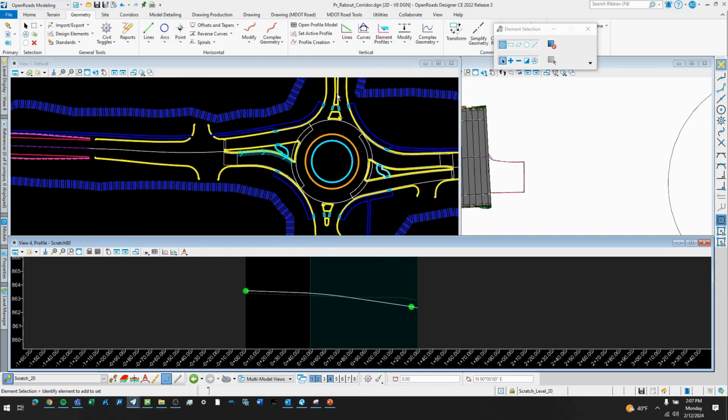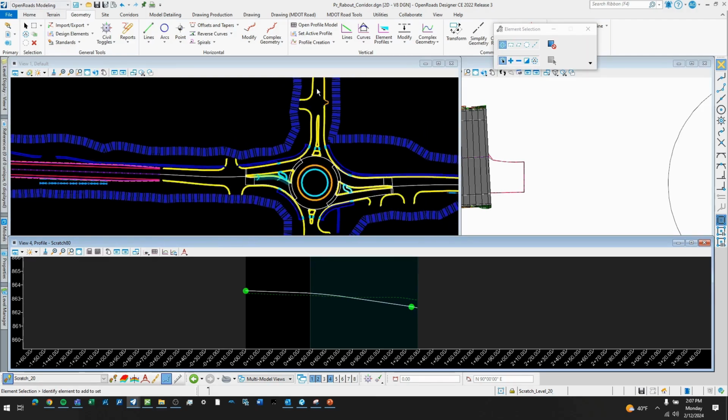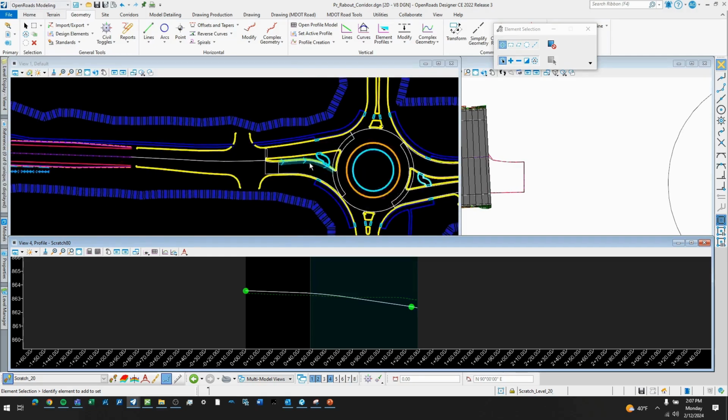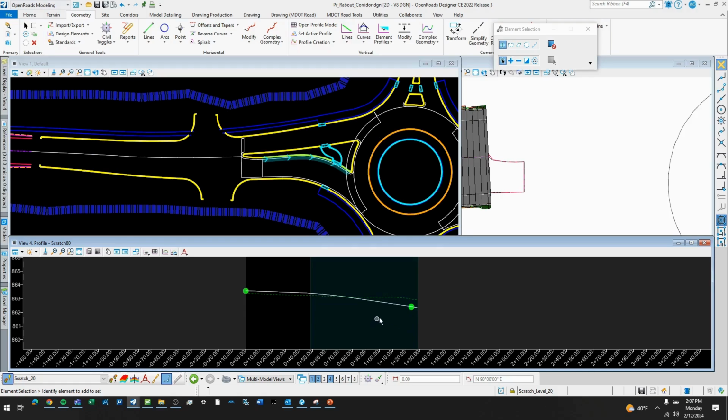In reality, though, there's no way all four of these legs are going to be coming up and into this roundabout. I know for a fact, like this leg, in terms of earthwork, it's already built up so high we're tied into existing. We can only tie in so far back. We're just not going to undercut and make this big curve to have it be smoother at the entrance. And ultimately, it's not going to be too big of a deal, they're going to be going slow, going around a curve and things like that. So I wouldn't worry too much, but keep that in mind.